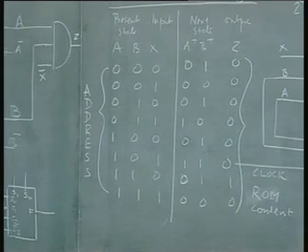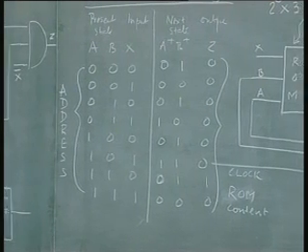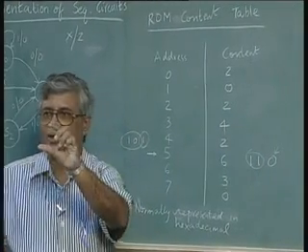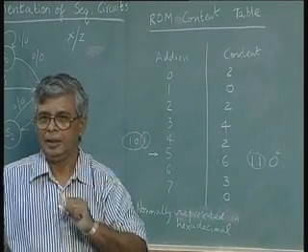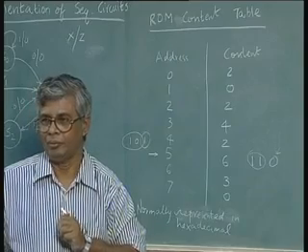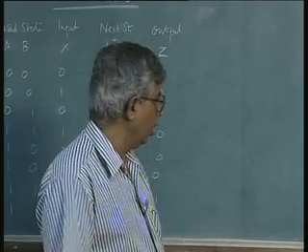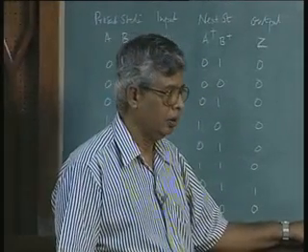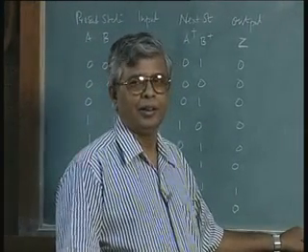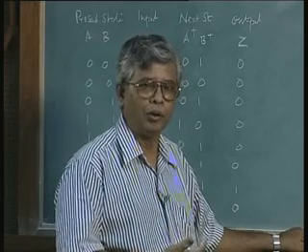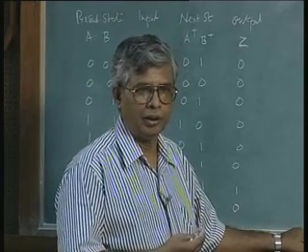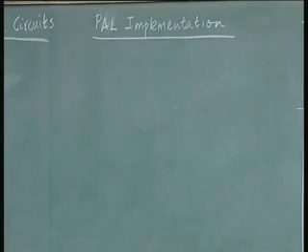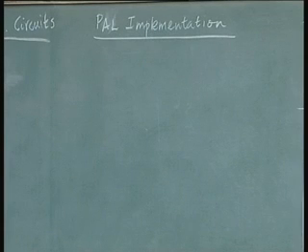A ROM of the correct size followed by 2 registers, I mean 2 flip-flops, which can be given as a single IC. So now I have reduced further. In the next level of simplification of the hardware, that means integrating the hardware, I am reducing the hardware count from the gate to multiplexer to ROM. Even in the ROM design we had a ROM and a register, which is 2 flip-flops.